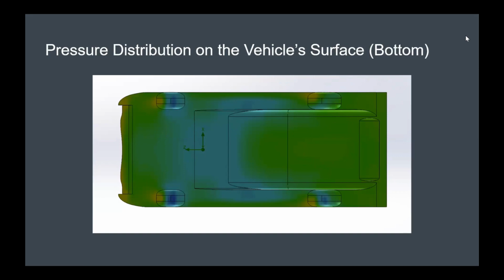And then here's our underbody view of the car. So we obviously have that giant low pressure region, which is great. We tried to increase the area of that region as much as possible. I think this is one of the main reasons why what Anna was talking about, the gradual angle increasing of the diffuser works, because you want to keep that area down there to help out with that low pressure suction effect, versus if you just sweep it up really, really quick, then the diffuser sort of steals a lot of that suction effect away from the underbody of the car.